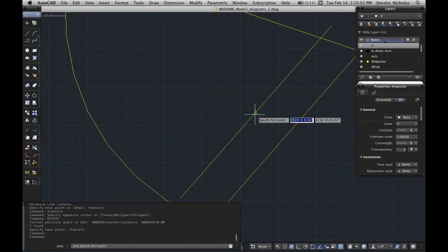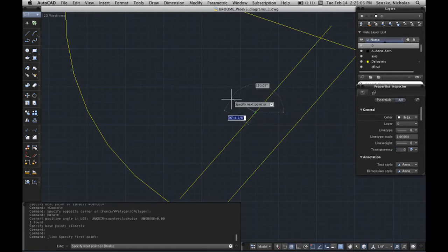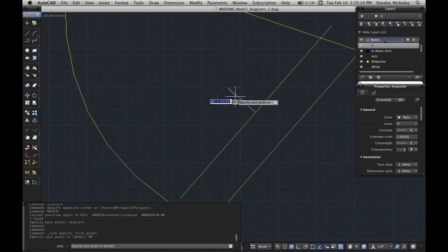Let's make a line. Same thing happens to me. I'm trying to use shift. Oh wait, there was a perpendicular. Okay, so if I'm making the line, and since I need a point on that line, I grab the midpoint. I have the perpendicular, and I can just say, okay, that initial mass of it is, let's say, another 50 foot. So if I do 50 foot, and I'm starting to draw that line, and it's got the perpendicular dynamic, I'm going to get a 50-foot line that's perpendicular.